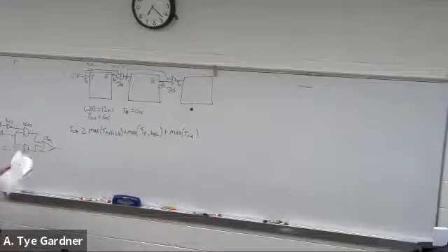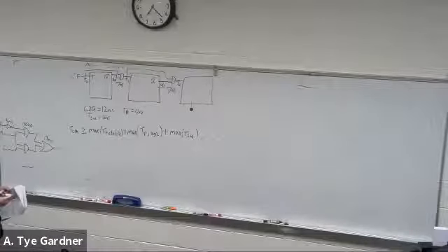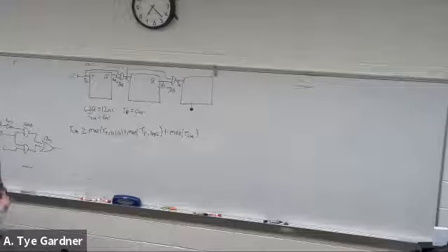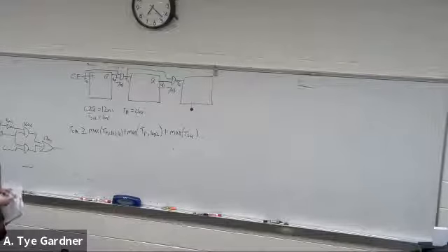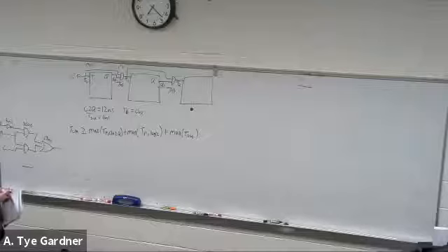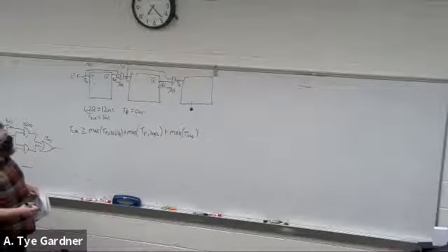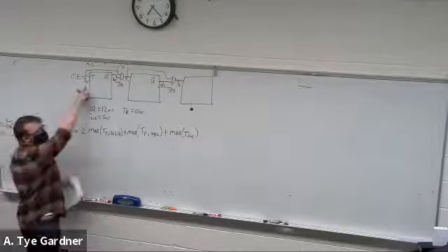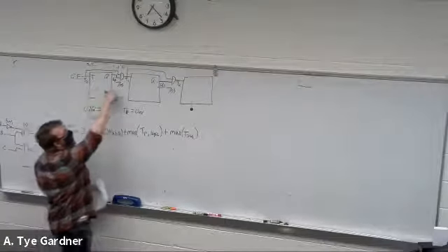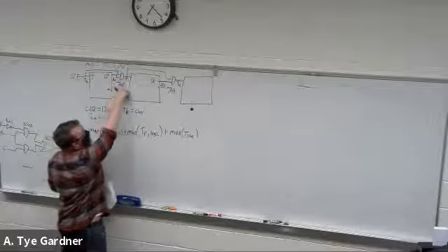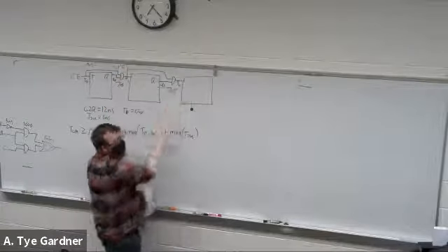Okay, so what we need to calculate here is what we call the propagation delay. So you don't have feedback per se, but we do have the maximum length of delays that we're going to have to deal with. And our worst one, because we don't care about hold times, we don't really care about the T0, is actually the flow from Q0 through this AND gate to T2.